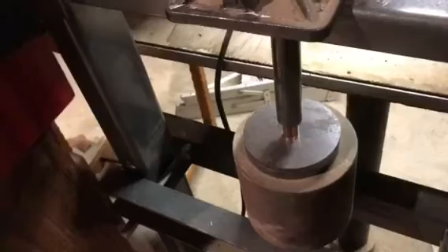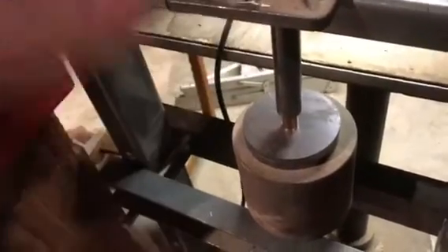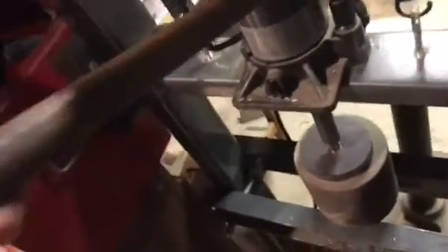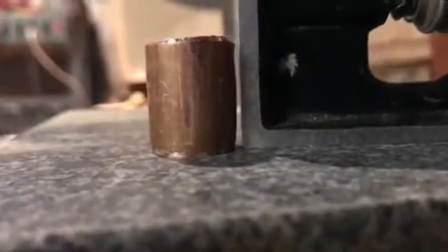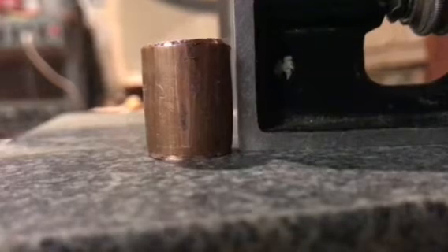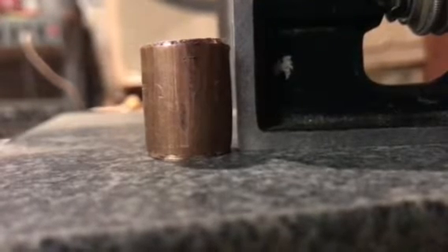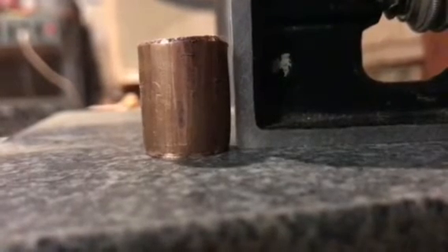At the hydraulic press, we can apply large amounts of normal force, but we won't need it because copper has a very low yield point compared to other materials. We can reach plastic deformation very fast. Here we can see the final diameter and length and the buckling of the part, just as it was in the SOLIDWORKS simulation.